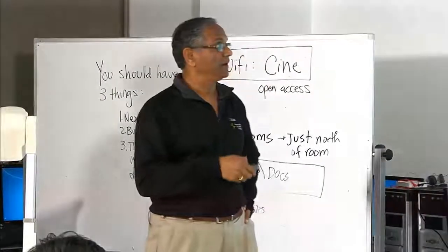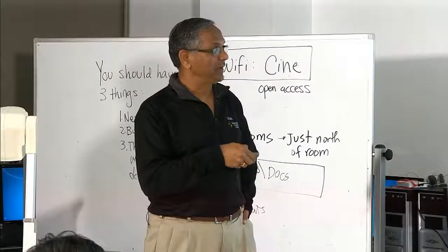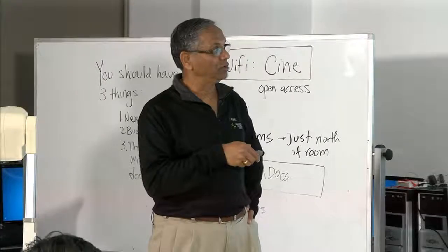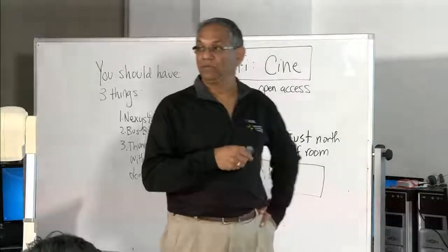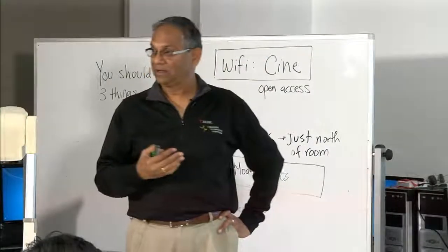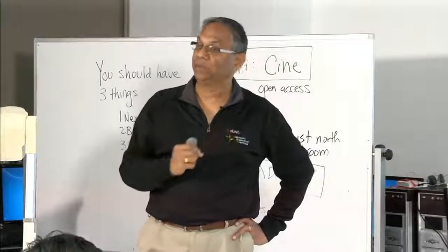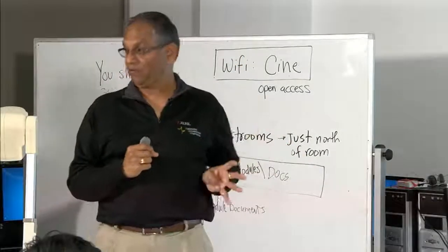latches, right? You can see also, though it's a little bit difficult, that the output of the lookup table can go straight out as combinational, or it can go through the flip flops if you want a sequential design. The other thing to keep in mind is that this has 8 flip flops.